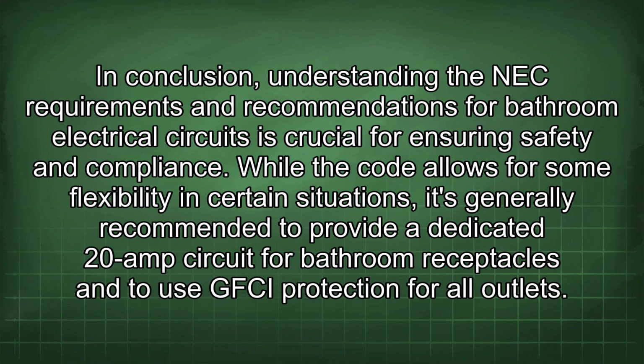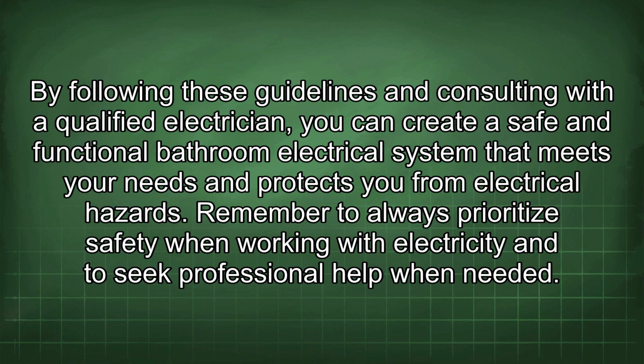In conclusion, understanding the NEC requirements and recommendations for bathroom electrical circuits is crucial for ensuring safety and compliance. While the code allows for some flexibility in certain situations, it's generally recommended to provide a dedicated 20 amp circuit for bathroom receptacles and to use GFCI protection for all outlets. By following these guidelines and consulting with a qualified electrician, you can create a safe and functional bathroom electrical system that meets your needs and protects you from electrical hazards.